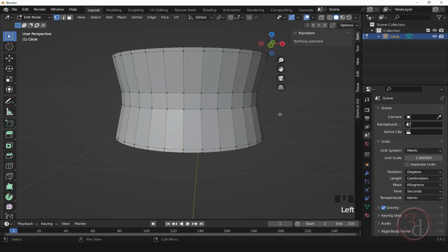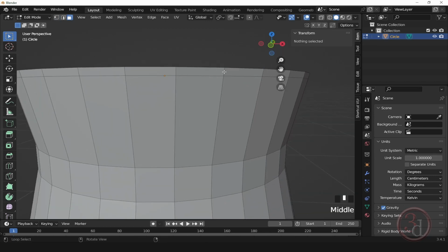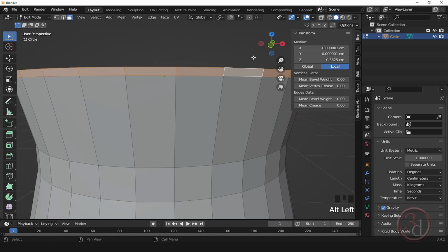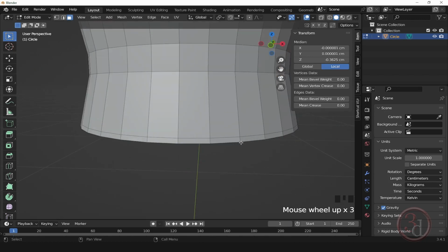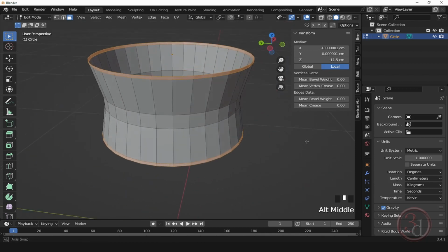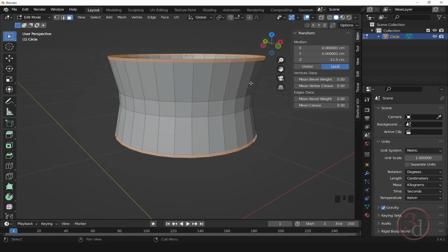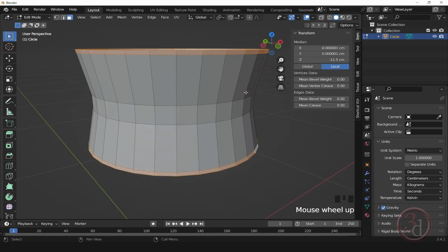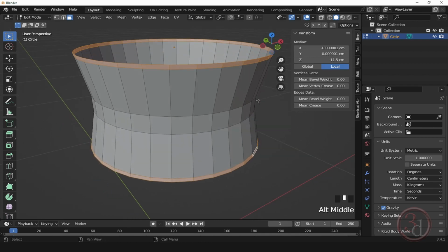And now I will make a selection. I'll switch to the face selection and alt click on the edge over here so that I can select the entire face loop. So alt click. All right, and then I will press Shift Alt click. Okay, and now what I will do is I will extract this. So I will press P on my keyboard and then click on selection.